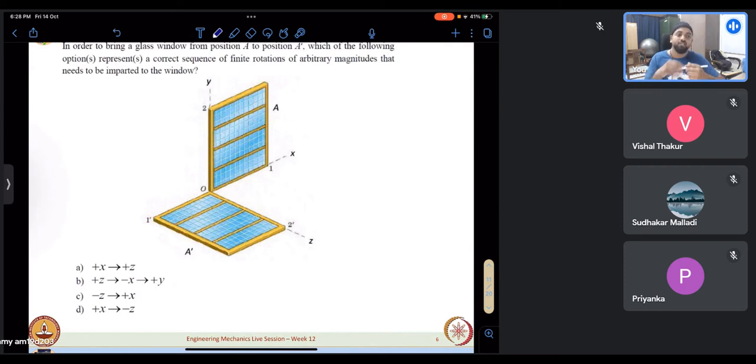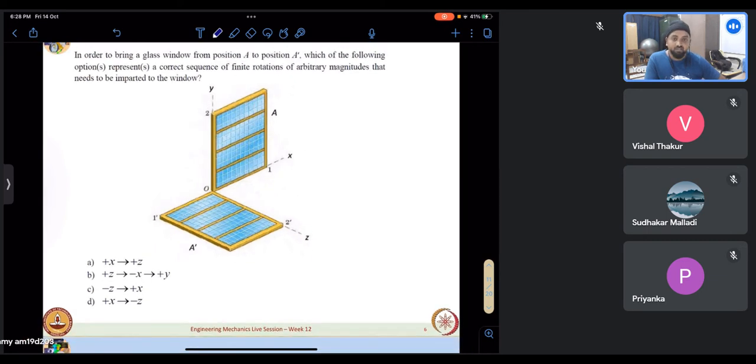If you see, the wheel is having a rotation, and then the arm itself is having another rotation. So we considered the infinitesimal case where it is just having a slight rotation, related the kinematical quantities, differentiated them, and got the angular velocity relation. That is how we have solved it. Whereas that is not possible when we have finite rotations. We can see this because these are not commutative. That is, they depend on the sequence in which they are imparted, as we will see in this problem.